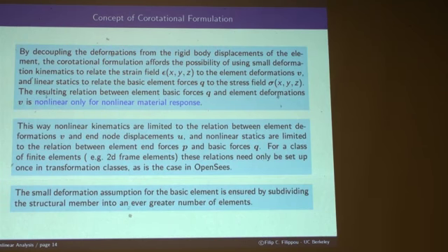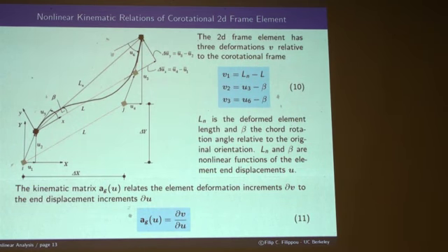Okay, so here is the general idea of the rotational formulation, which we are big subscribers of, and whoever does not like to use it will be complicating their lives unnecessarily. But you're welcome to do so. I have no objection to you complicating your lives if you want. By decoupling the deformations from the rigid body displacement, basically what I have done here is identify the deformations, and by describing the deformations and forces relative to a system that rotates and translates with the element, I am removing the rigid body modes from here.